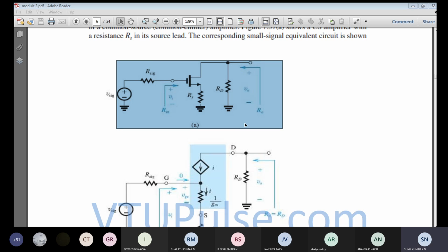Okay, so now I am going to say this gate is connected in a T form. This is a gate, this is a drain, and this is source. So this is the gate which has been connected over here, so Ig is equal to 0, and this drain terminal remains the same. This is the X point, which I have not labeled, but this point is nothing but the X point only. So this point is the drain terminal. Here you can see the drain current is flowing from the drain terminal to this node, the current Gm into Vgs.